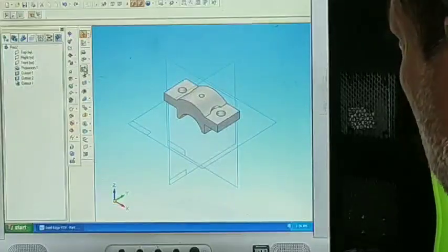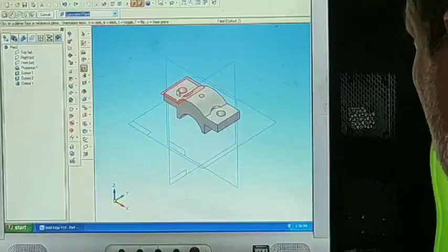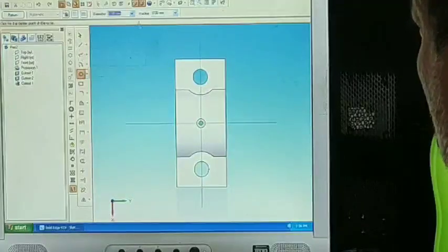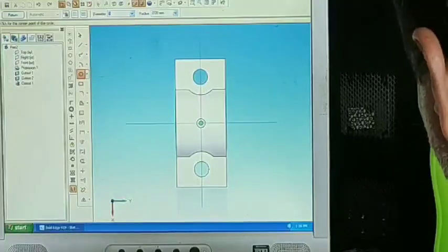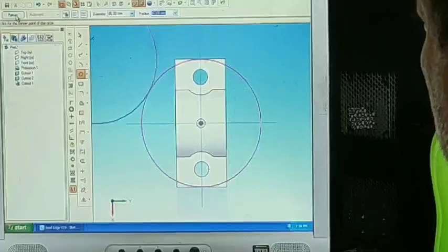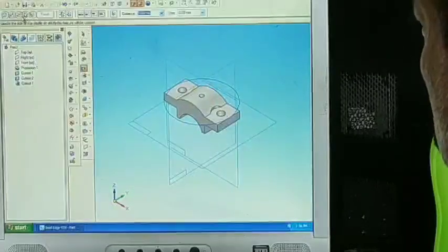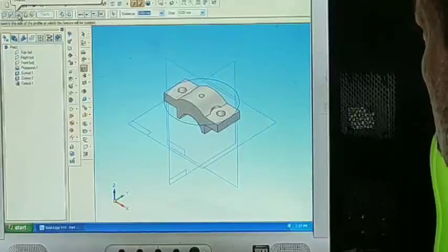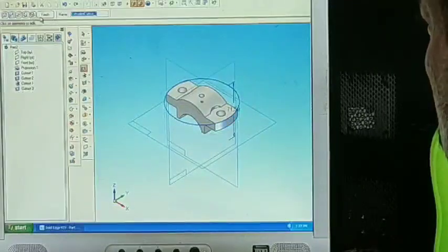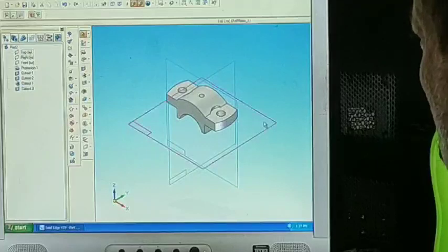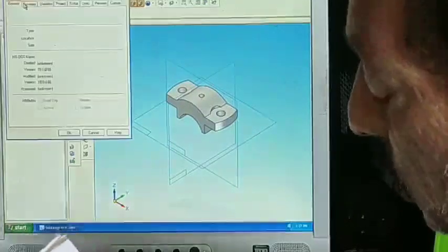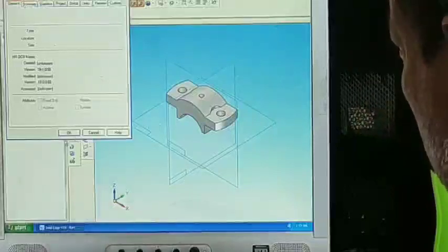So once again go to cutout command, select this face, circle of diameter 86, place it in the middle, return. This is cutout side step, outside, downwards, finish, cancel. Yes sir? Save it. So save. This is cap of plumber block.